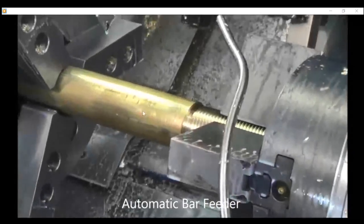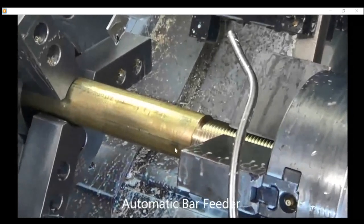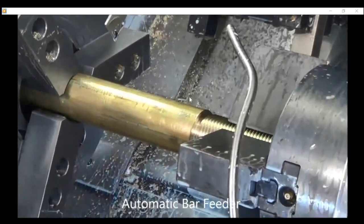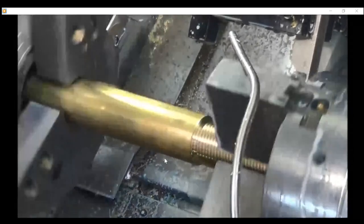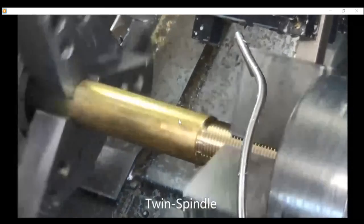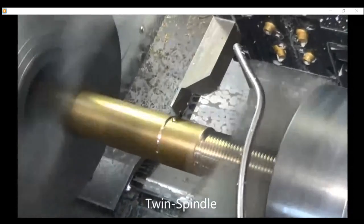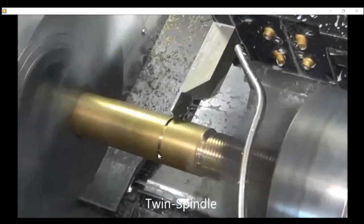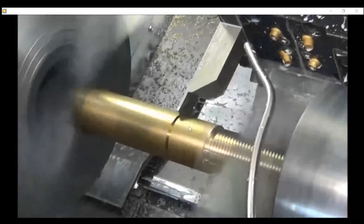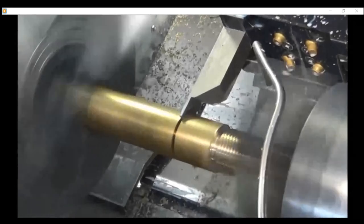And now we need to cut. I believe you remember this one. I saw you before; this is not the first time you saw this video. Then the tool here will rotate. Now it is rotating. This tool penetrates in the radial direction to make what we call the cut off, to separate the workpiece material.